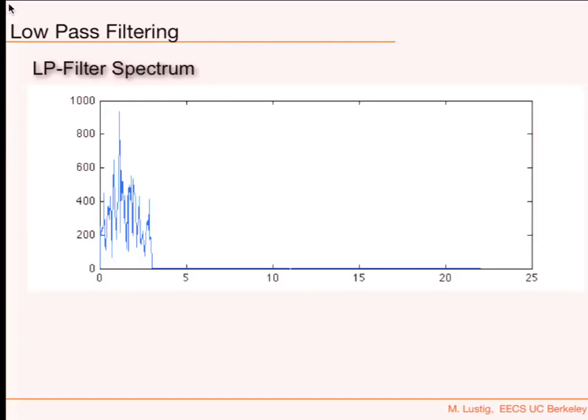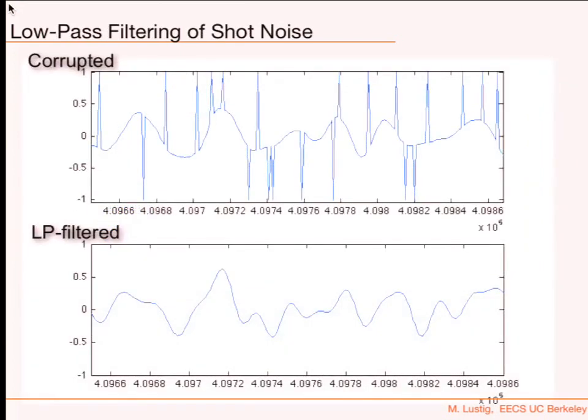It's kind of difficult, right? Not very good quality, right? The problem with shot noise is, it spreads everywhere, but it really spreads also on your particular signal, right? So it's a significant amount of noise that's going on. Low-pass filtering reduced it, but didn't eliminate it, okay? Let's look at the time signal and see what the corruptions are, okay? And here's why it was not that effective.